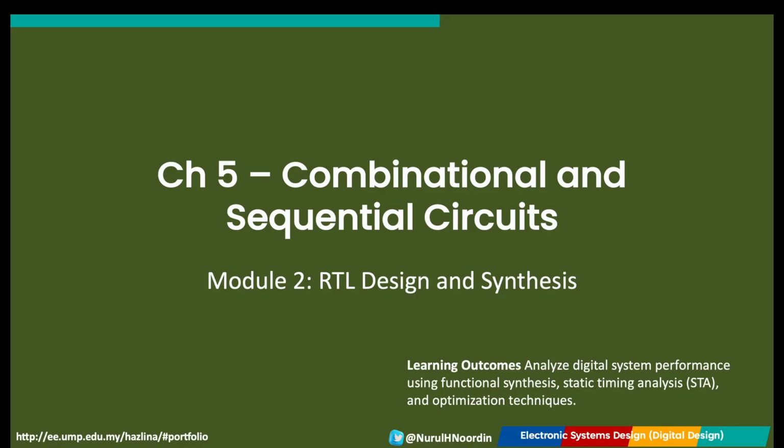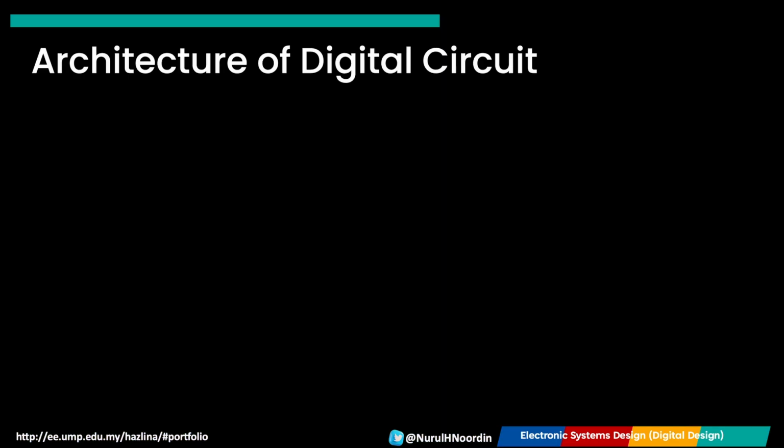Hi, welcome to chapter number 5. Today, we are taking a massive leap into our FPGA journey as we explore Register Transfer Level, RTL Design. At this level, we are describing the true behavior of our digital circuits in Verilog by focusing on data transfers between registers and combinational logic. Let's break it down into two main pillars.